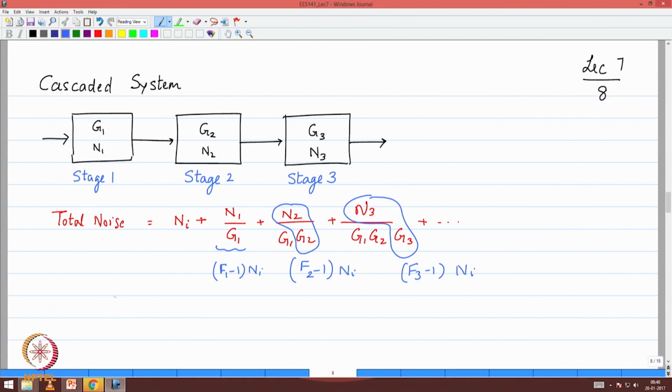the effective noise, this is what we get, and this is a famous equation that you would have been familiar with, which says that the overall noise figure when I have a cascade is equal to F1. That means if there were no other components, F1, that is traditionally how we have understood receivers to function. But if there are cascaded terms, the second one will contribute F2 minus 1 divided by G1, F3 minus 1 by G1 G2, and so on.